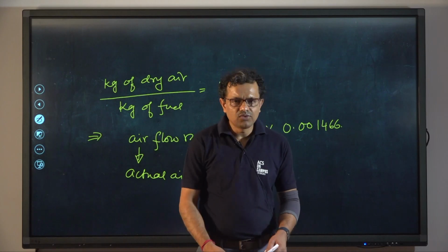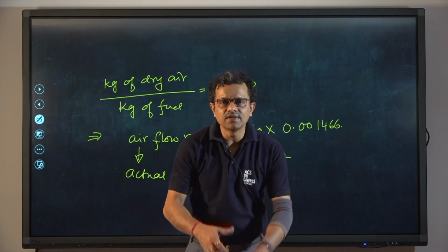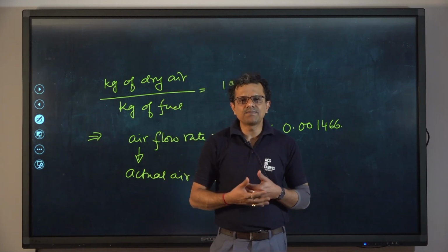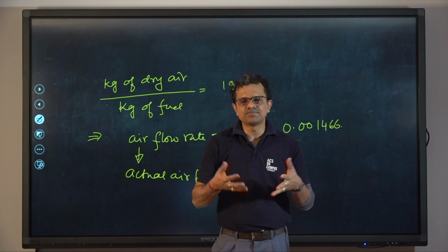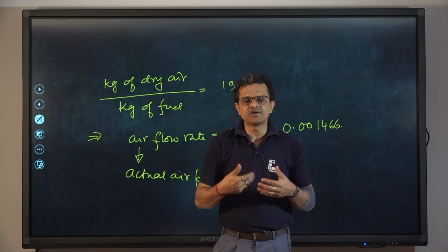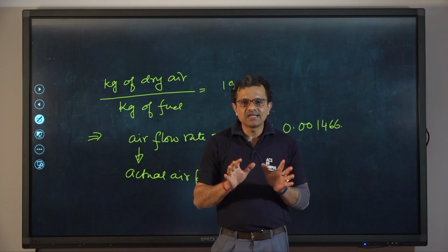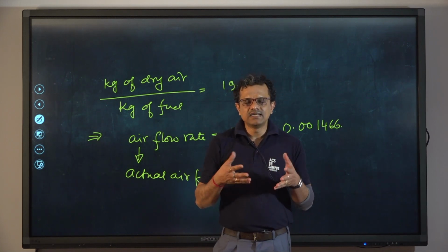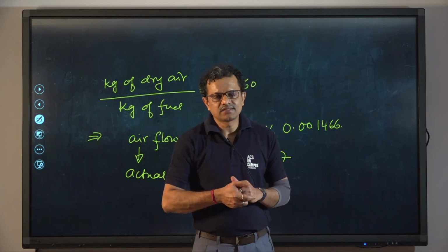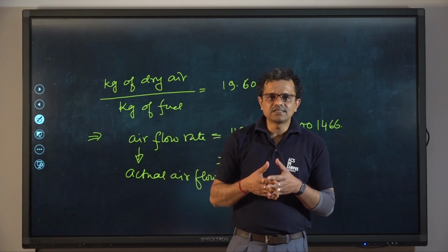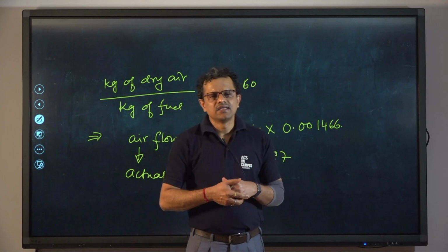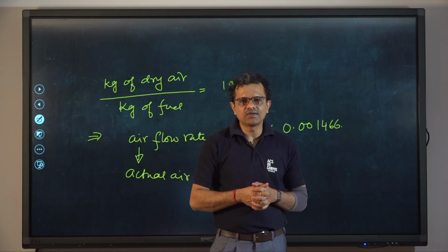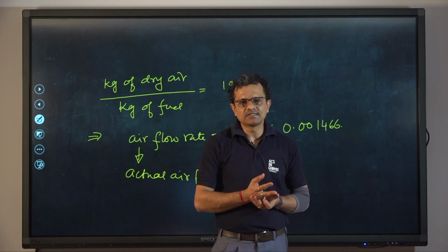Okay. So, we have discussed the measurement of volumetric efficiency, which is very important to know, because if we supply more air to the engine, more fuel can be burnt and the power output will be more. But there are restrictions provided by the air cleaner, intake manifold, inlet valve, and all these parts. Accounting for resistances from all these parts, the actual airflow rate to the engine cylinder should always be less than the theoretically calculated value, and hence volumetric efficiency is defined.